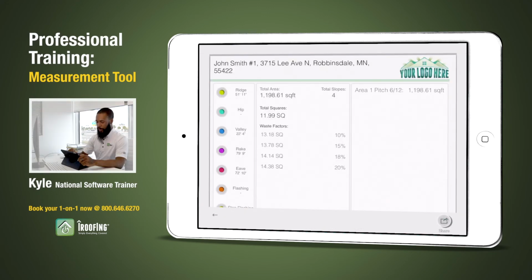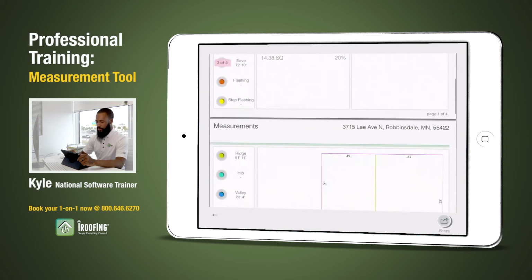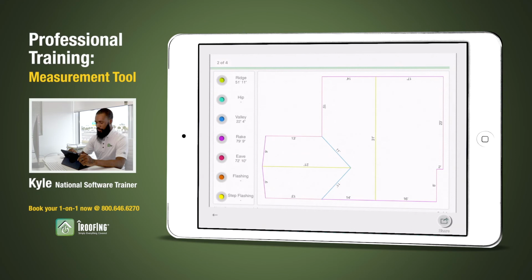So with this roof, without waste, I came up with a total of 12 squares. If we look directly below our total, you can see that we've also got our waste factor, so we can go with a 10, 15, 18, or 20% waste, which is already calculated for us. If I scroll down to the second page, here I can find my diagram of the roof with each of my lines color-coded based off the labels that I used.